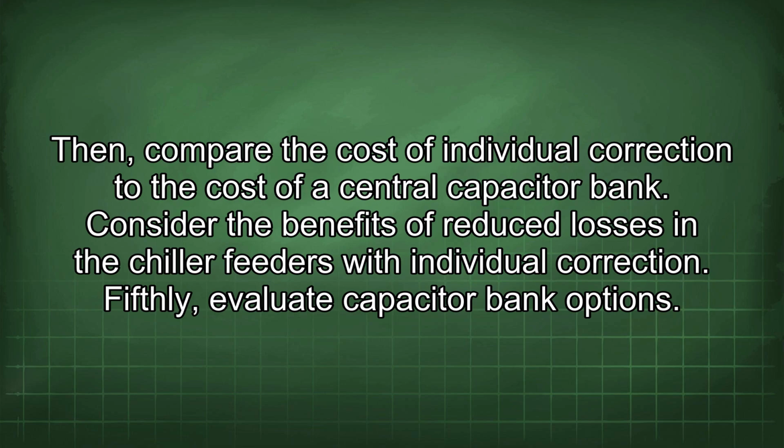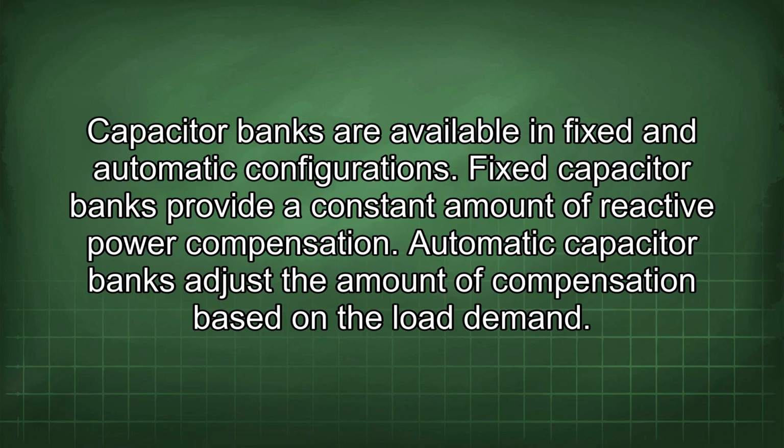Fifthly, evaluate capacitor bank options. Capacitor banks are available in fixed and automatic configurations. Fixed capacitor banks provide a constant amount of reactive power compensation.